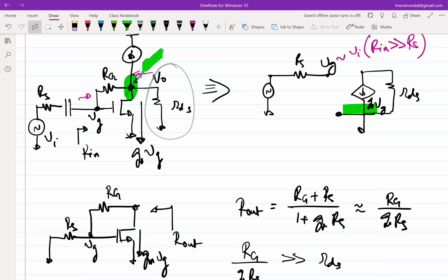We are doing all these things because we want an integrator, right? So when you say we want an integrator, what is meant by that? This is an error amplifier, and the output of this error amplifier is proportional to the input voltage times some proportionality constant, the current that is GM times VG. And I know that I have to feed it to a capacitor to get an integrating action, right? So ultimately, there will be a capacitor added here when you are putting it in the loop. Now this entire contraption makes it a first order circuit.